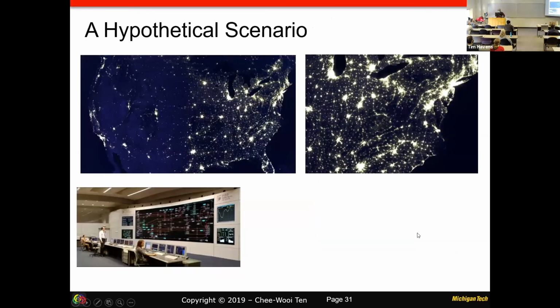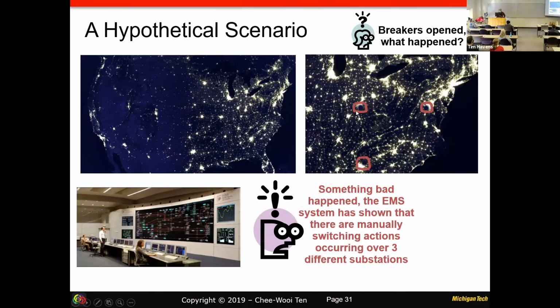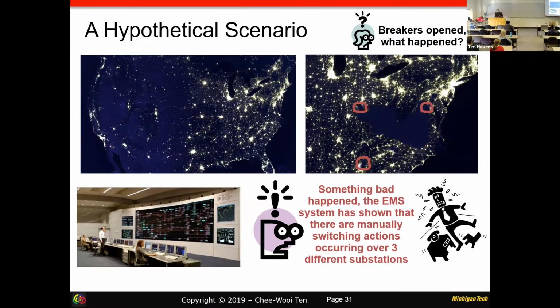And this is a diagram I thought I should show you, of how a power system outage would look. Say hypothetically, the Northeast system has been hacked and compromised, and attacks have been carried out at 3 substation locations in the geography. The people in the control room will certainly get some input in terms of alarms coming into the system, because circuit breakers opened, and some of the alarm information set in the logic of the control system will come all the way together. That is one thing, but the grid itself has to balance the total generation and total load. So that cascading effect will really kick in later on.